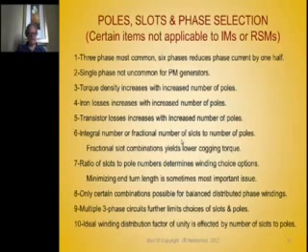If you must use a radial flux motor and you have very minimum axial space to put it in, you've got to keep these end turns low. So your best choice in that case is to use a fractional slot winding, a pole and slot combination where the coils are wrapped around a single tooth so that the end turns are real short.